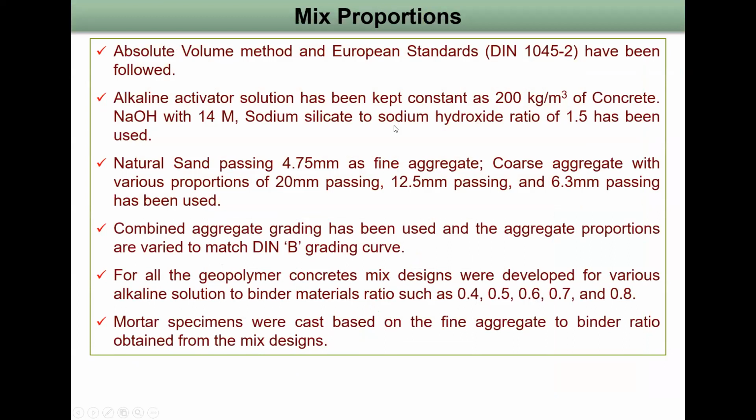As the design mix methodology, we followed the absolute volume method, and for gradation purposes, the DIN standard has been used. Based on a lot of initial trials, we have fixed the alkali activated solution at 200 kg per cubic meter and the molarity at 14. The 14 molarity was fixed based on the initial trials, along with a sodium silicate to sodium hydroxide ratio of 1.2. All these constraints were fixed based on the preliminary experimentation.